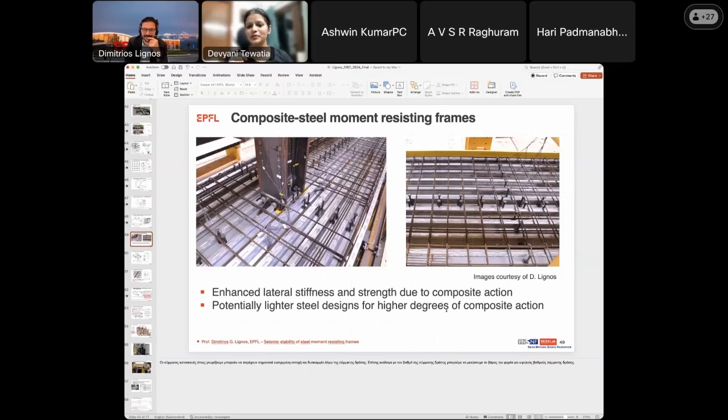What should be the limit on inelasticity in the panel zone? Okay, so the current rules allow you to go up to 4 gamma y. And then if you talk to some of the offices, they will tell you that generally we prefer to keep it elastic because we're not certain, if you go to 4 gamma Y, what exactly it means.